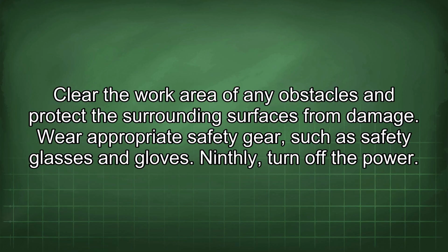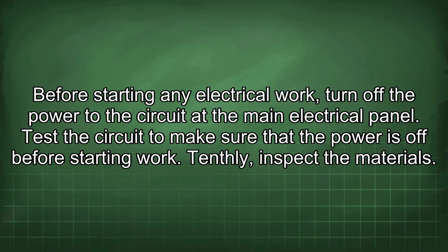Wear appropriate safety gear, such as safety glasses and gloves. Ninthly, turn off the power. Before starting any electrical work, turn off the power to the circuit at the main electrical panel. Test the circuit to make sure that the power is off before starting work.